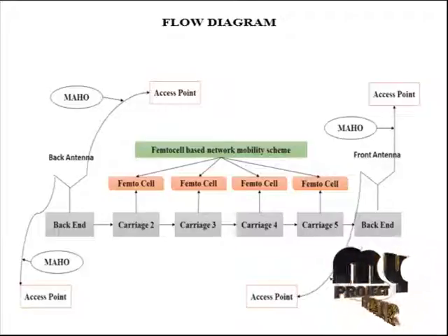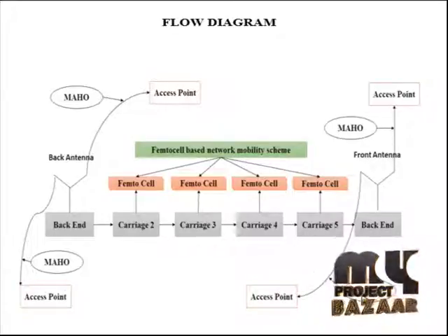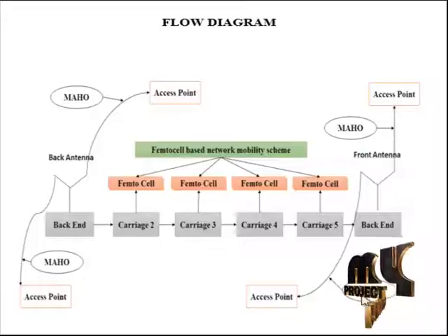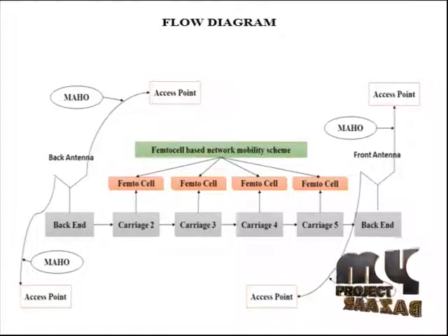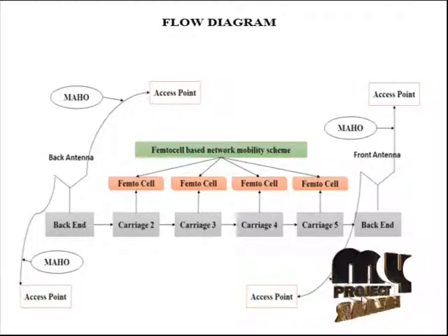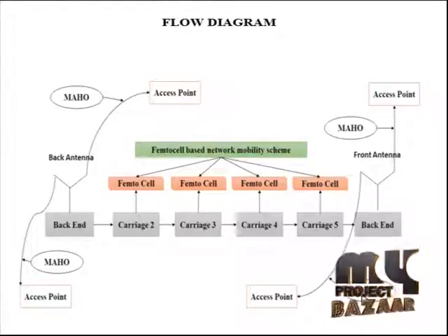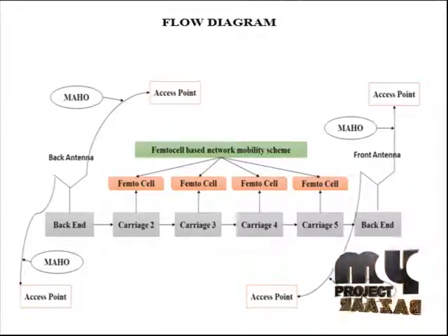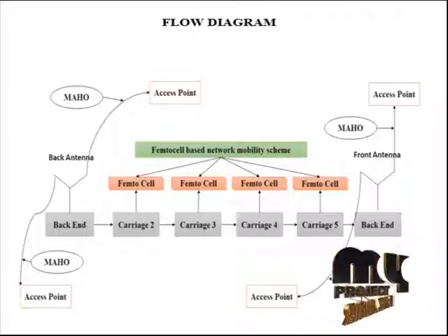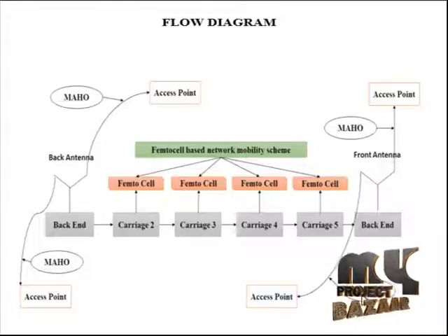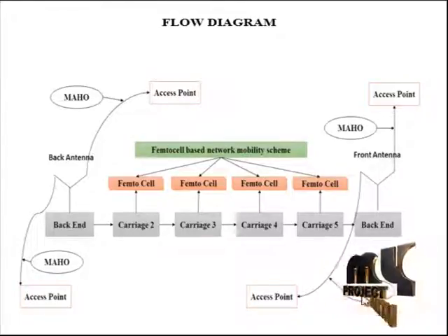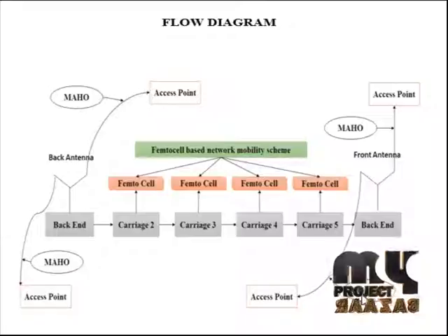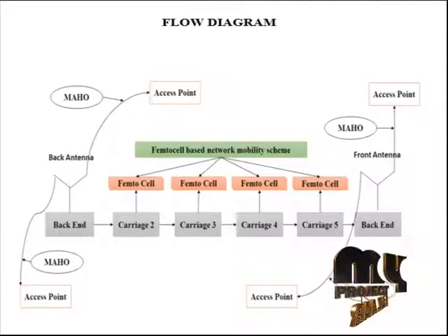Next, in order to improve the MAHO algorithm, we propose the zero forcing algorithm. The zero forcing algorithm, or interference nulling algorithm, refers to a form of linear processing algorithm used in communication systems which nulls out the interference signal in the time domain and inverts the frequency response of the channel in the frequency domain. If the channel response for a particular channel is H, the interference nulling algorithm multiplies the input signal by the reciprocal of H, which removes the effect of the channel from the output signal.